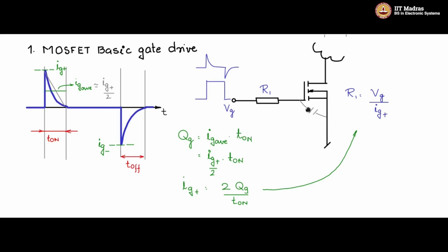So whatever charge is there in the internal capacitance will discharge through R1 and the external Vg circuit. Therefore you get this negative pulse and charge removal. This way the MOSFET will be turned on and off. Remember, you need some charge to turn on the MOSFET.